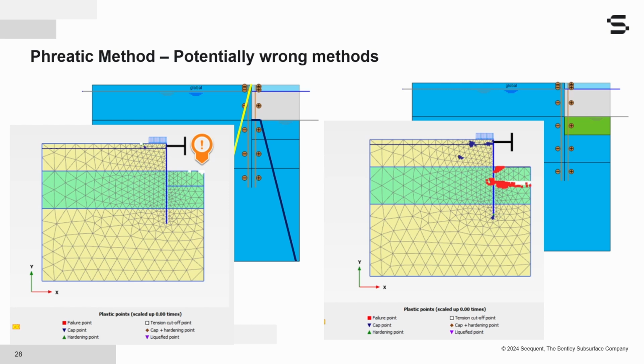We see that here the pore pressure distribution just below the excavation bottom is not zero. And since there is no resistance at the top of the excavation, so we have no excavation and we have no load, then we might get into some kind of heaving problems. And since, in this case at least, there is no tensile strength, the soil will fail locally in tension. So we get some heave, and as you can see here, we have some white plastic points near the excavation surface at the bottom.